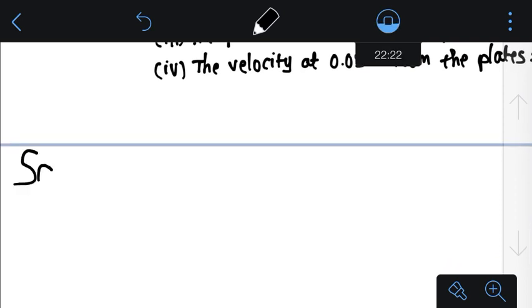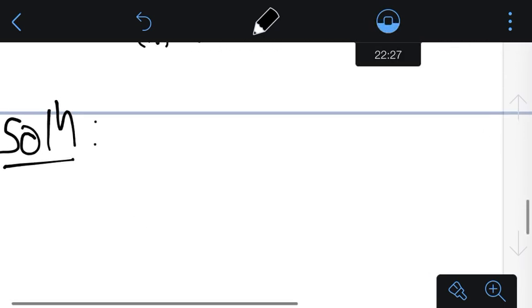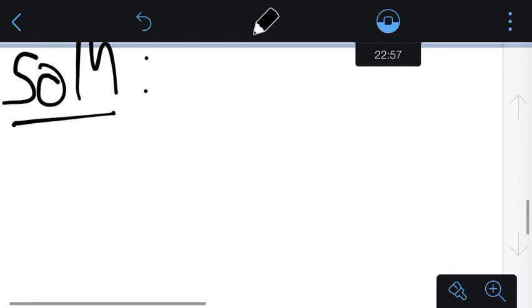So in terms of solution, we can begin with discharge first of all. Now if you want to calculate discharge, we know that average velocity is discharge by area. So we have to multiply area into average velocity. Area is available considering the unit width of the plate, but u average is not available. So first of all we have to compute the average velocity.